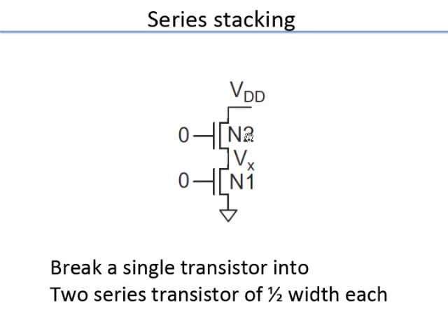Of course, you can also say, why not increase the channel length? I'll make the channel length 2x. You can do that also, but sometimes, if you recall the threshold voltage as a function of channel length, you have short channel effect and reverse short channel effect. Sometimes threshold goes up, sometimes threshold comes down, depending on the process.